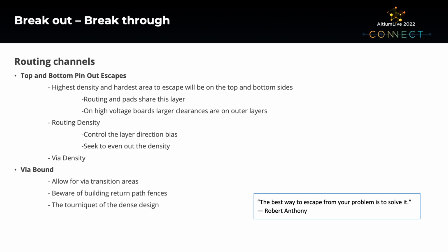Then we also have high voltage boards that have very large clearances. Those can give us real hard challenges with routing escapes. And then routing density.